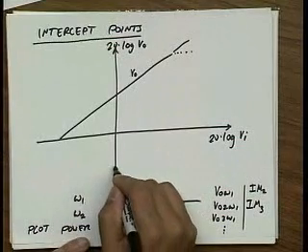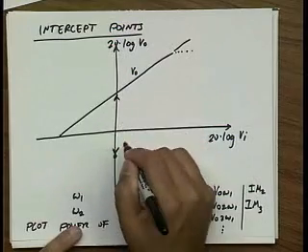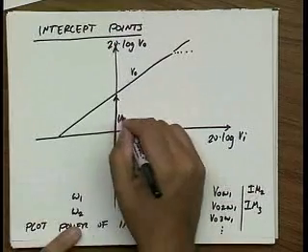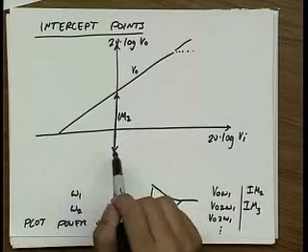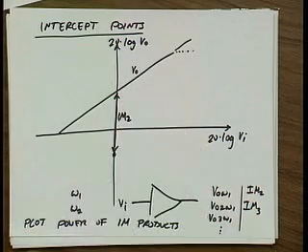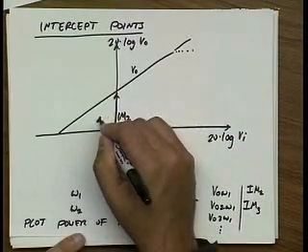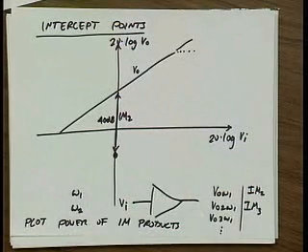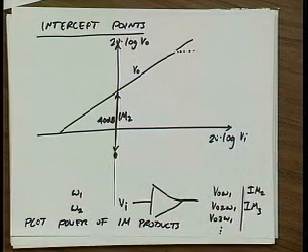In particular, let me look at the power. Let's say I go out here and I measure that at a certain input power, my IM2 is down by this much, right? So IM2 is a ratio between the intermod component and the fundamental component. On a log scale, it's just this difference. Let's say, arbitrarily, this is 40 dB. That at a certain input power level, my intermod power is 40 dB down from the fundamental. Well, how does it vary with input? If I vary my input, what happens to this intermodulation component?